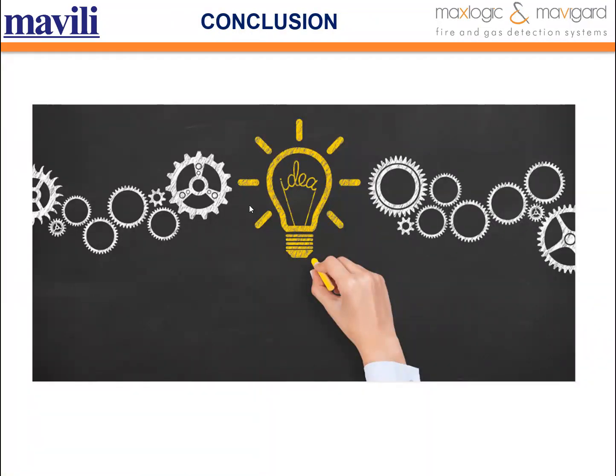As a conclusion, before choosing the detectors that we will use for early detection of fire, flammable substances that pose a fire risk for each location should be determined, and appropriate detectors should be selected according to fire effects like smoke, heat, or flame.